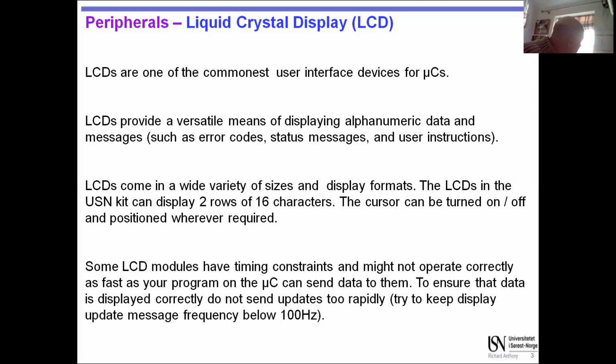Because it's only a short jumper-wire distance from the microcontroller, I'm using it in parallel. I've got 8 data wires and some control wires connecting to a port on the microcontroller. And in today's sample code, that is the way I'm assuming it. I'm hoping you have an LCD that is capable of that. Yeah, we have. Brilliant. Again, because they do sometimes change these kits and it would mess things up a bit.